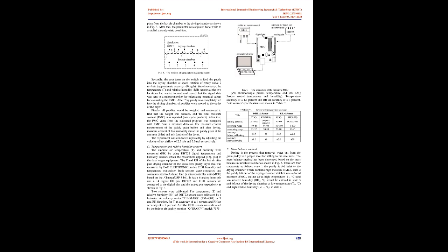The parameters were as follows: the hot air temperature of 130 degrees Celsius, the eccentric speed of 110 rev/min, and the velocity of hot airflow of 2 m/s, which was measured by an Extech Instruments thermo-anemometer, Thailand, with a basic accuracy of plus or minus 3% m/s. The temperature inside the hot air chamber is measured by a type K thermocouple, with 5-point installations along the chamber as shown in detail A. The thermocouple connects to a data logger with an accuracy of plus or minus 1 degree Celsius.